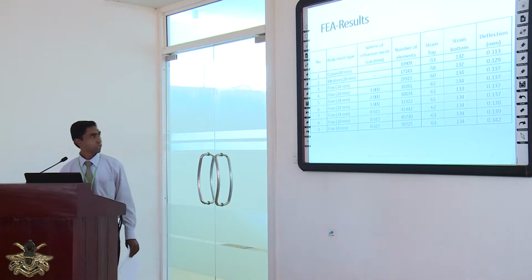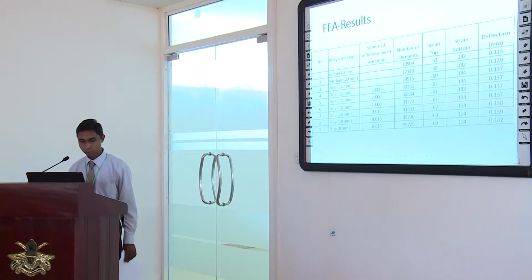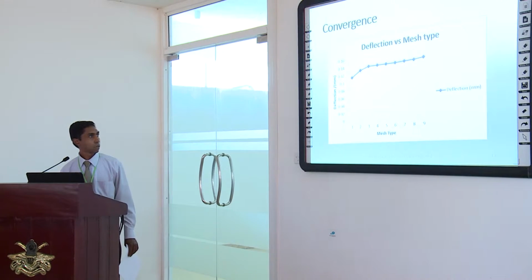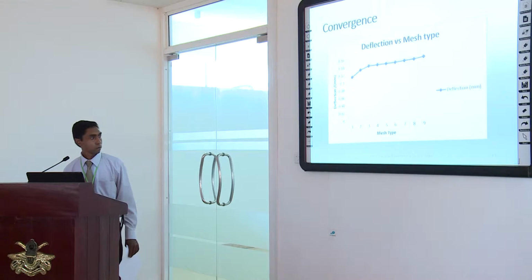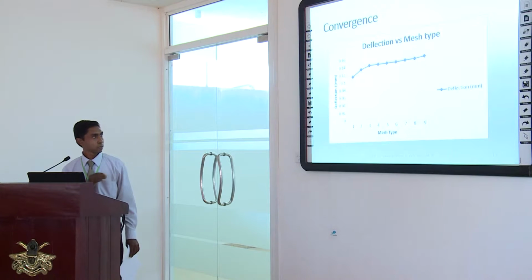We gradually reduced the element size of the mesh, and the relevant results were obtained: strain and deflection. Next, I considered the convergence of the deflection. After that, you can accept the result of the finite element model, because there is a convergence of the result.